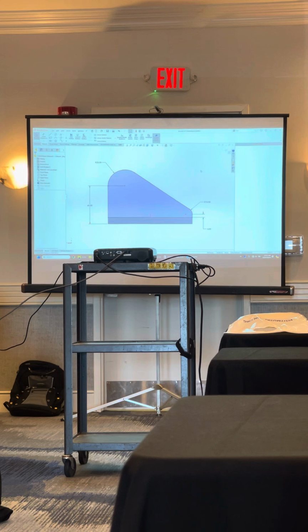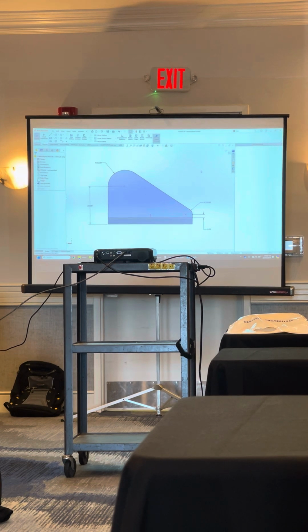And so you'll put the dimensions on, but you'll still have blue geometry. So the first response of most people using SolidWorks is throw more dimensions on. They throw one dimension on, or it defines that, they delete that, they throw a different kind of dimension on, and all of a sudden everything turns black, but now they have extra information in their sketch that's not needed. But I found if you go through the distinct phases, draw it, test it, then dimension it, it gets rid of that quite a bit. And you have a better understanding of how your sketch is going to update as it moves around. Kind of cool? All right, so no special button, but definitely a mindset.